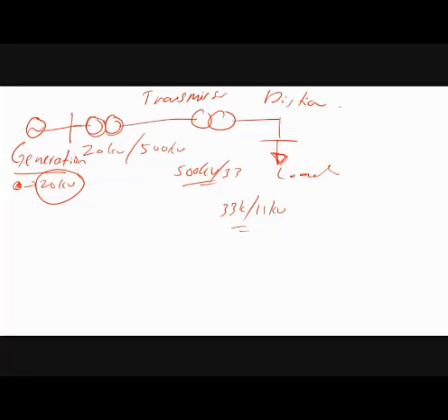I always say, why do we have to use high voltage? The importance of high voltage is to reduce power loss, reduce voltage drop, reduce cable size, and reduce cost. These are 4 points that you have to remember all the time, because this is the basic question that will be asked when you apply to be an engineer, especially in TNB.